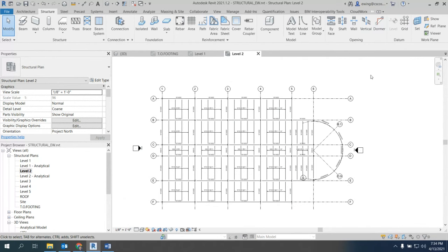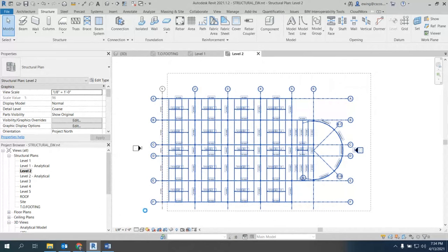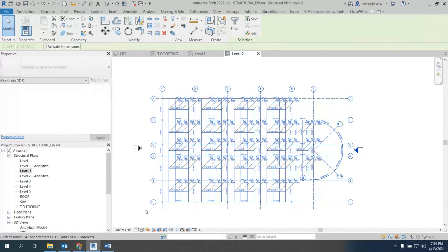So let's pick a window just like this. And notice this is the 3rd time we've done this kind of thing tonight. But this one takes a little longer because we're physically selecting everything. So once you get to the lower left-hand corner, just let go of your pick button. And we can't just copy all this stuff because Revit will just not respond, right? So we have all this stuff selected, okay?